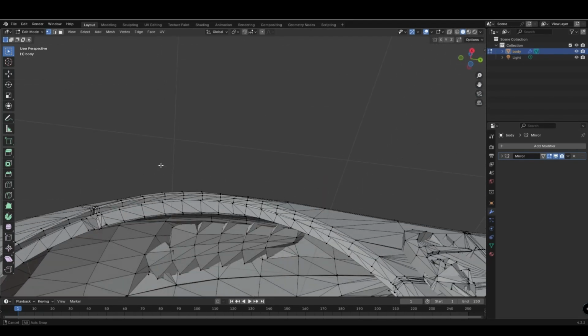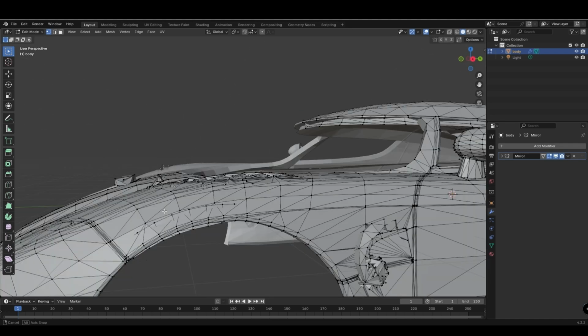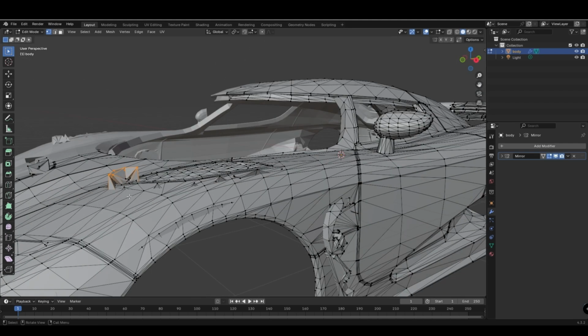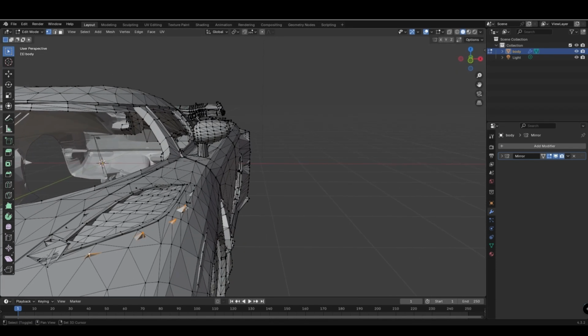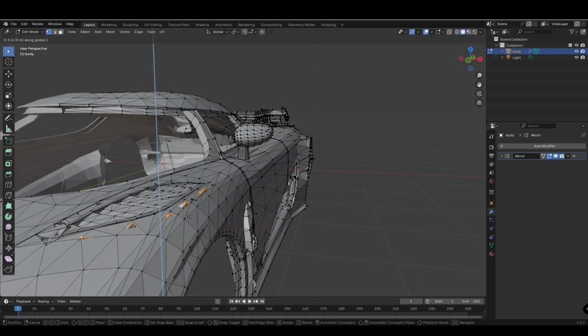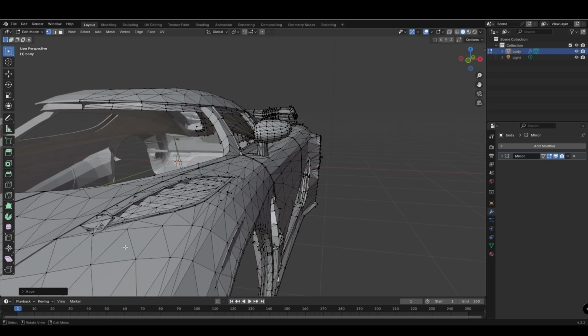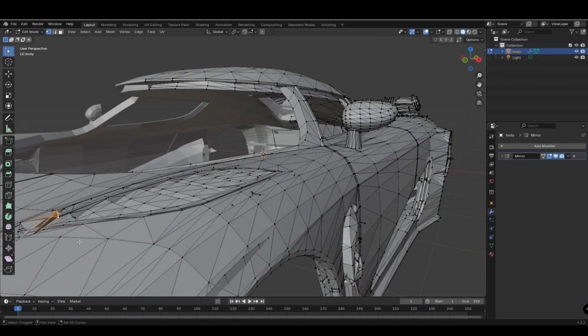Other areas of the body, you may just want to move the artifacts below the top surface of the model, as deleting these may put holes in the body shell. So select a few similar points at a time, press G to grab them, and then here we press Z to lock the vertical movement, and then move them under the model surface.